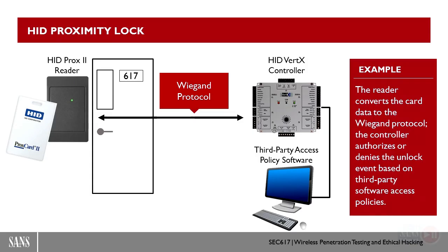Oh, someone just badged in and I now have their card number. I can potentially take that card and then do it from the command line to clone it. The better one is now I'm communicating with it over Bluetooth, and I can select and replay. It takes that number and translates it back to the Wiegand protocol, injects it to the wire, and then the door opens. The ESP key uses an ESP8266 Wi-Fi module.